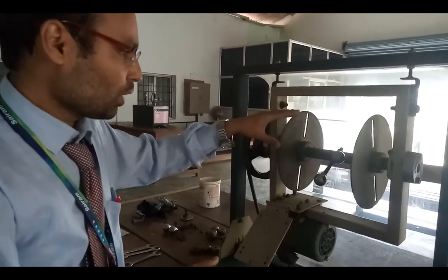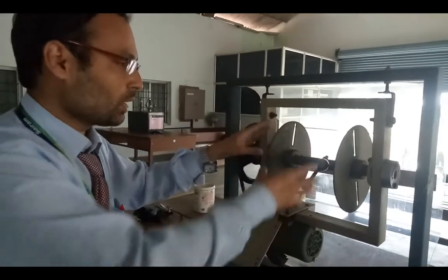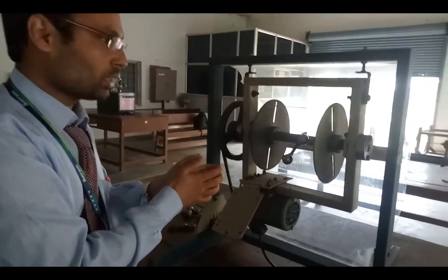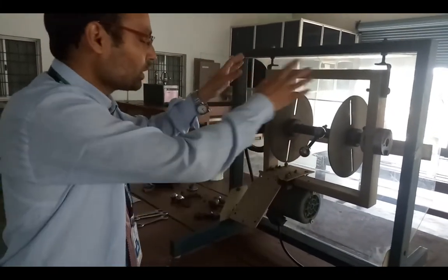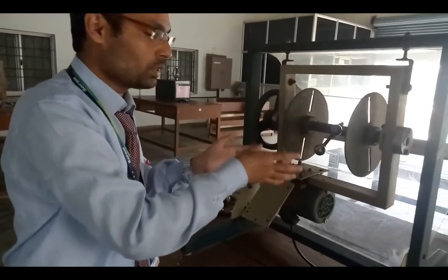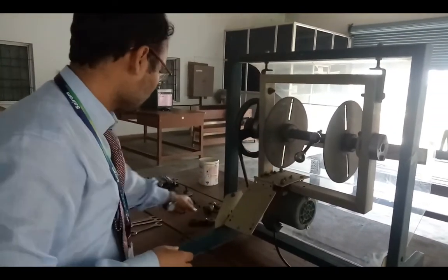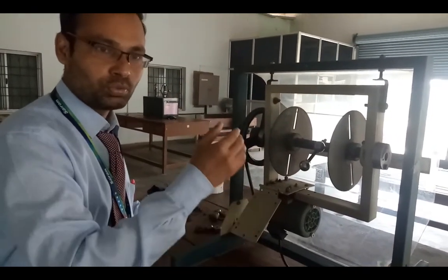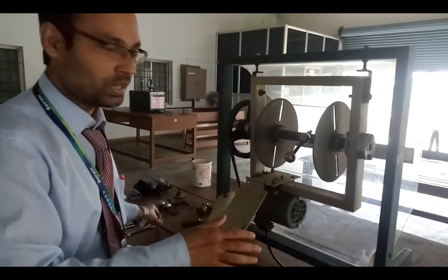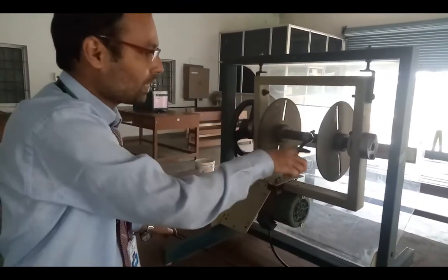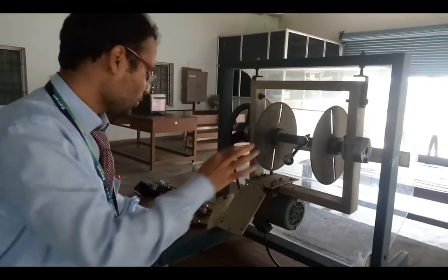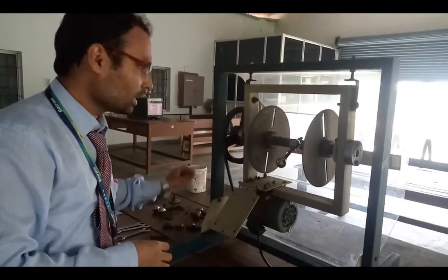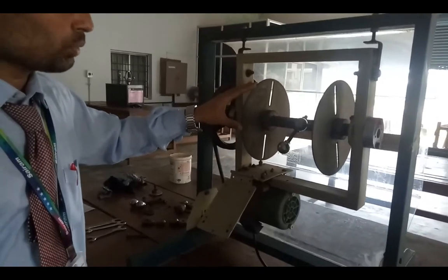If you start the machine, the balancing setup is going to vibrate. The main aim of this experiment is the balancing of rotating masses. If I start this machine, the whole body is going to vibrate. To control that vibration, we are going to measure some weights. With the help of the calculation part, we find out the masses of A and B, or rather C and B, and we fix those masses in the opposite direction. Then the whole body is stationary, that is, we control the vibration. That is the main aim of this experiment. I will repeat: the main aim of this experiment is to control the vibration.